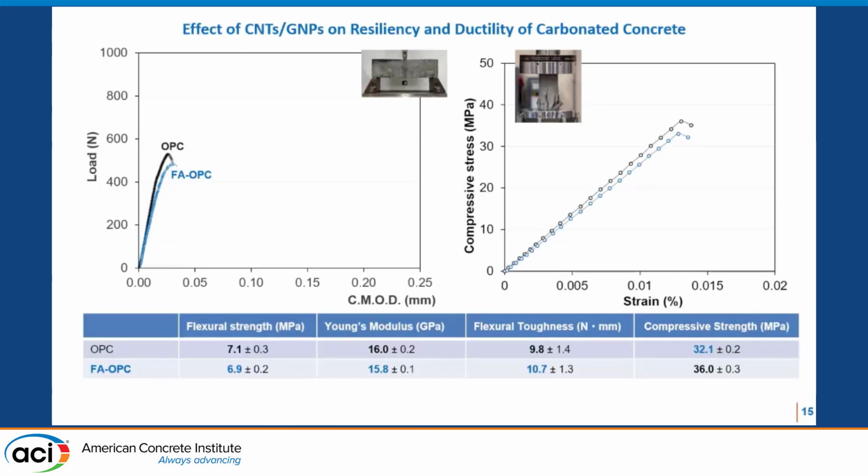To be consistent with all the work that we are doing, we examined the mechanical properties. We ran the mechanical property tests for all mixes in this work. Very briefly, we are very well aware that carbonation increases the brittleness of all cementitious materials. Of course, this is accompanied with loss in ductility. Both phenomena are together.